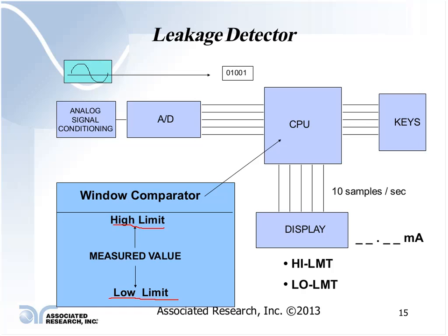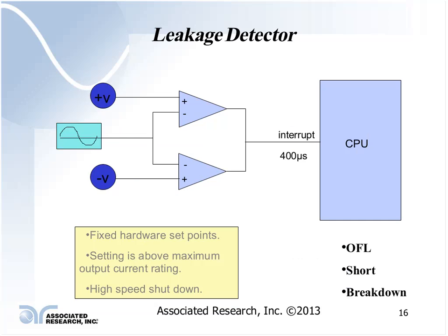And some will tell you just to use a 120 k ohm value, and your tester must signal a failure within half a second once you apply the voltage across that 120,000 ohm resistor. The low limit is not specified. That is more of a quality issue that is done from your standpoint to make sure that you are doing a test on your product, and it's also helpful in, again, making sure that you are in fact testing a product each time you go through and do your test.